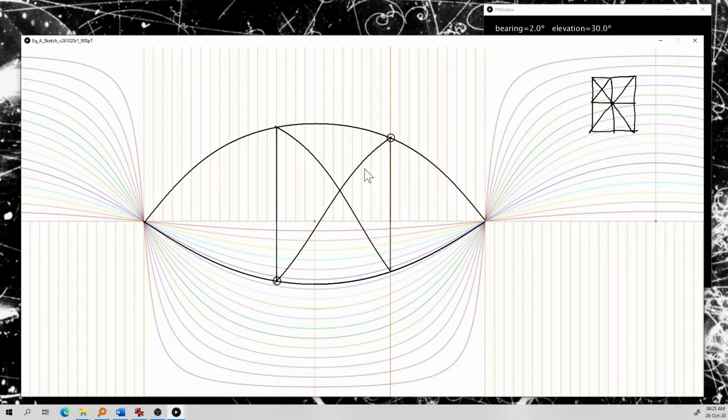Okay, so here, exactly the same thing that I have done. I set one point here, the vanishing point, another point here, press N here and M here, and I pass this horizontal, which is this one here on the orthographic view, and the vertical, I can obtain it because, as we have seen last time, verticals project as verticals in equirectangular perspective.